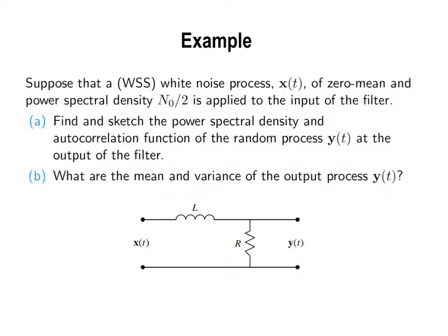Isn't thermal noise in the transmitter and the receiver, but we model it only in the receiver? No, only in the receiver. Because we are modeling the noise added to the transmitted signal, not a signal inside the electronics of the transmitter, right? So we always care about the signal coming out of the antenna, which is already after everything in the transmitter, and then we have a signal, and then after that, it goes through the channel, then we collect it at the receiver, so the noise is added at the receiver. Okay?